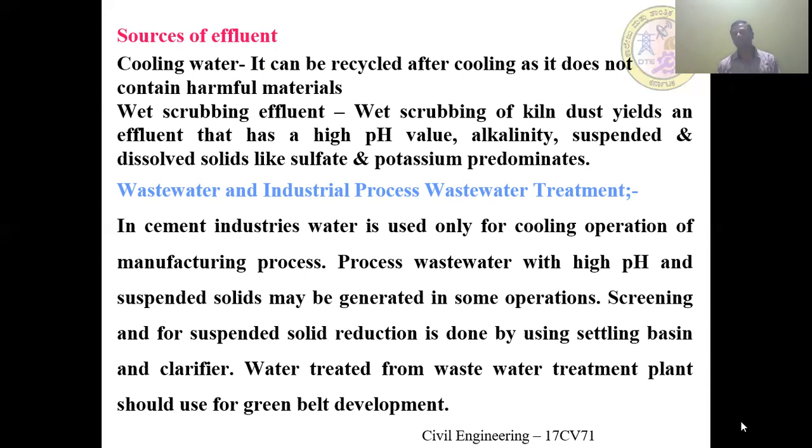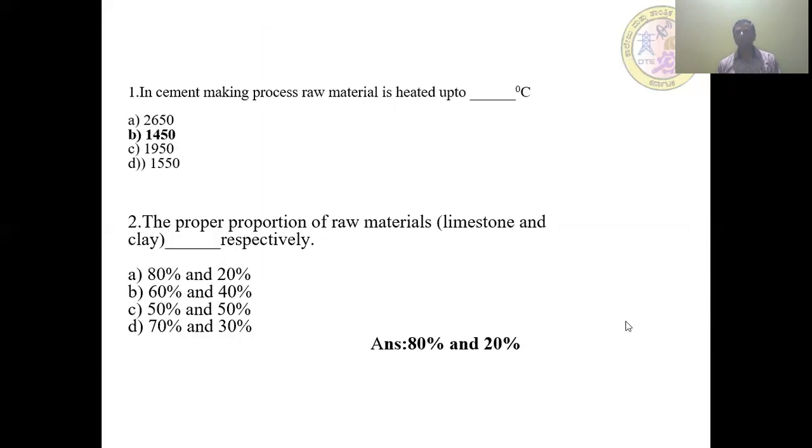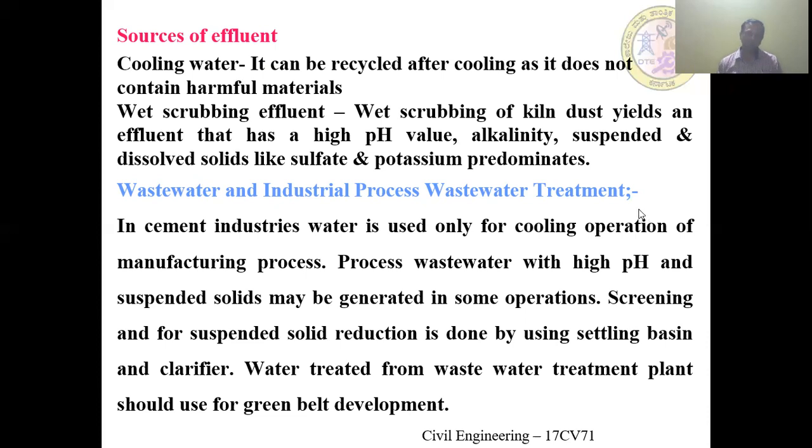The clear water can be used for cooling purposes. In this way the wastewater treatment for cement industries is done. No microbiological process is involved here, since there are no BOD and COD values. It has only some suspended materials or pH changes.